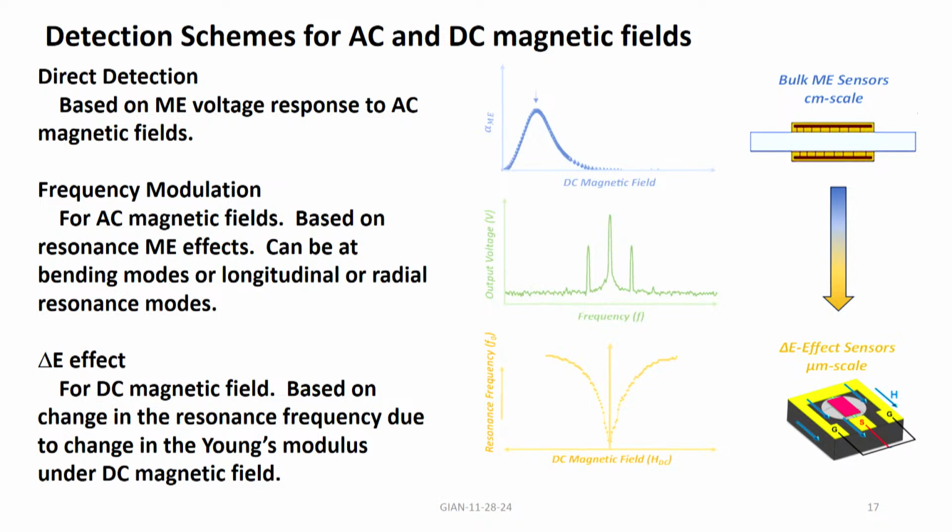So, the question is, how do you increase the sensitivity? The answer is, use the resonance mode to your advantage. How is it done? You always have a driving field which will drive this composite into longitudinal resonance at a few hundred kilohertz, for example.